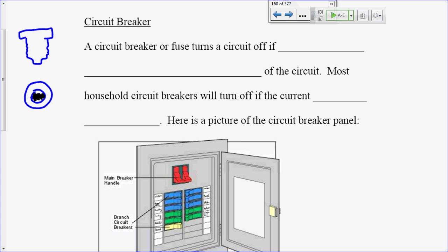On your circuit breaker, you also have a main breaker handle on a lot of the newer houses. That means you can turn off electricity to your whole home, right? Just turn everything off all at once, and that disconnects you completely from the street side service. So if y'all are in hurricanes, I'm not going to tell you how to energize your whole house. Have y'all done this before? You're not supposed to do this. You plug it into a high voltage, and a lot of people do it, but you're supposed to turn off your main circuits because it'll feed back into the line. Right. And any of the energy people who are working on the lines may not know, because they're assuming, hey, everything for miles is off.